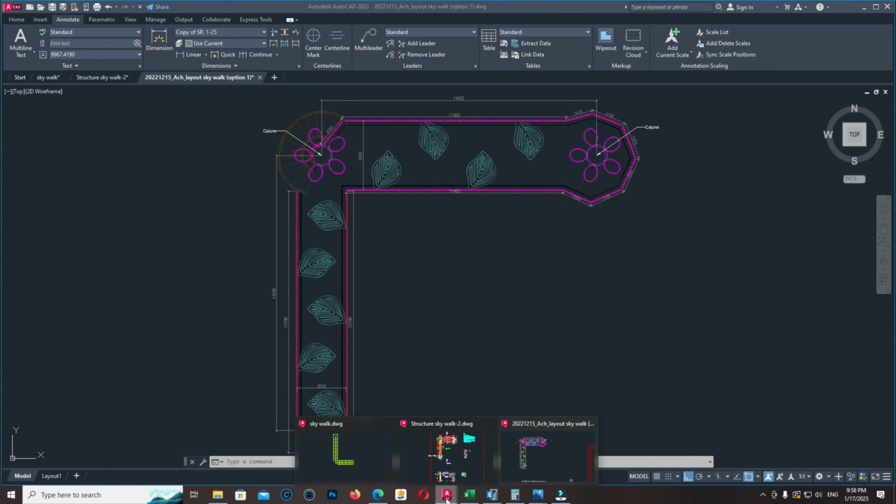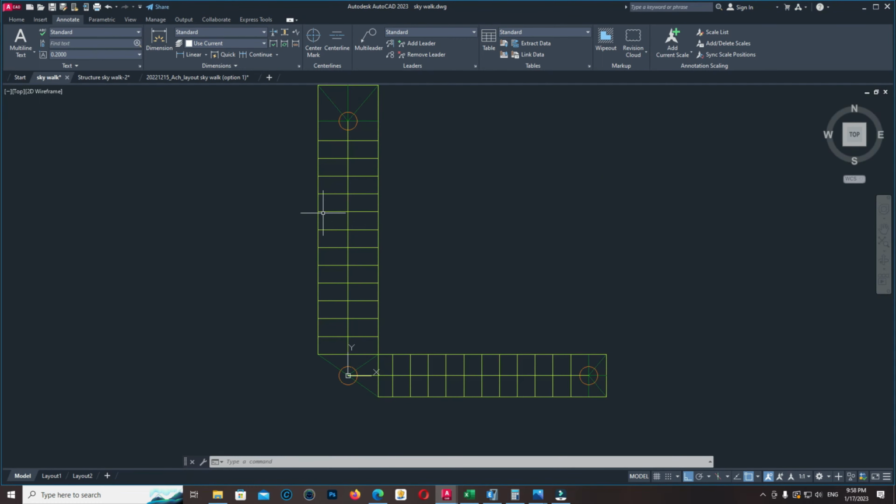The easy way to model the complete structure, or any shape in the architectural model, is to model it in AutoCAD as elements and export as a DXF file to import into ETABS. Now let's start. Like this one, just throw it in the AutoCAD.